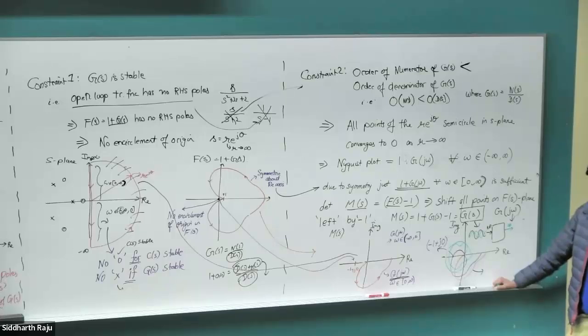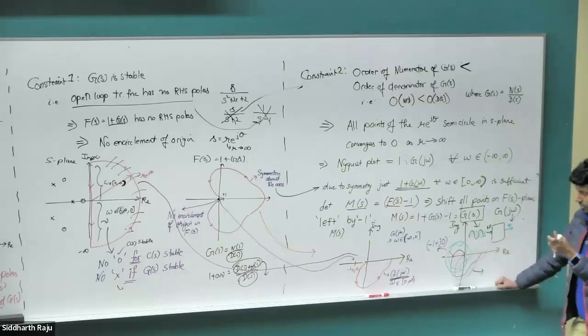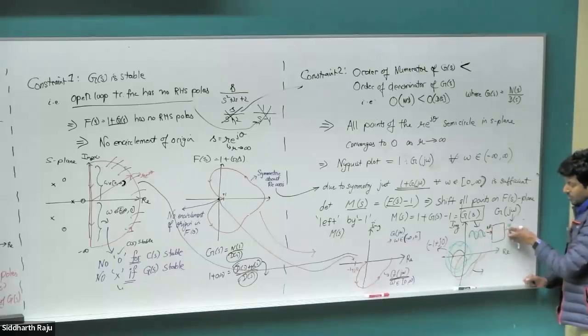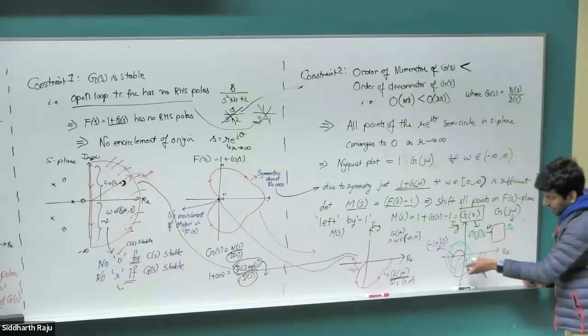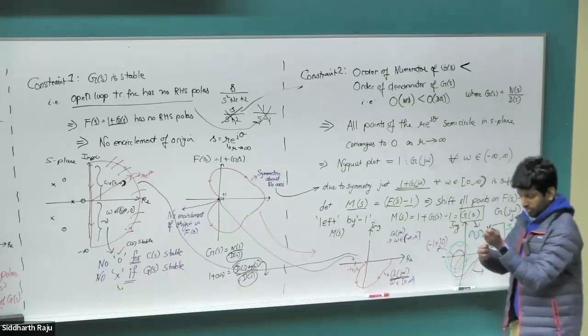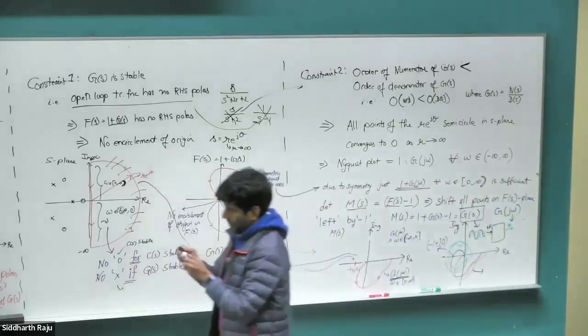There are multiple reasons. You could have done some parameter estimation wrong, but quite commonly the problem is that you didn't have sufficient phase margin. I'll get to the term in a second. It's very close to almost becoming unstable. And then you have your ADC signals, you have some kind of filter, which all adds phase delay, right? When you have an RC filter, and then your ADC is taking some time to sample, and your code is taking some time to execute, all of this adds delay in your signal. So you have some input and it is getting phase shifted before it becomes the output because there's a huge amount of delay. And the delay is basically rotating the signal in the Nyquist plane so that it starts to enclose the -1 plus j0, and what was previously stable becomes unstable once you put it in the hardware. Okay. Everybody clear so far?